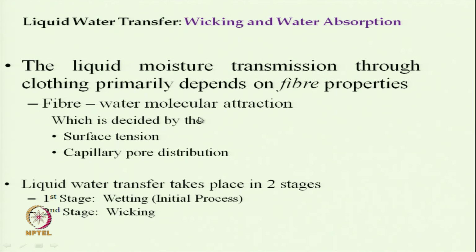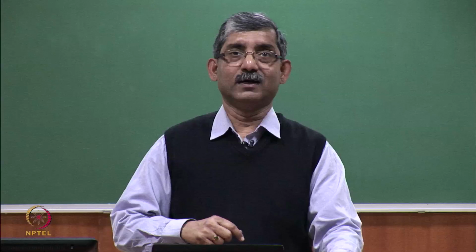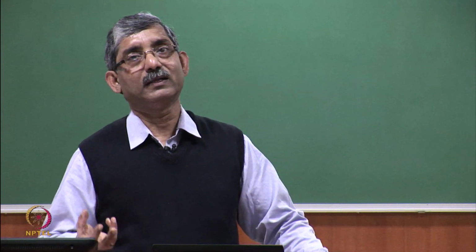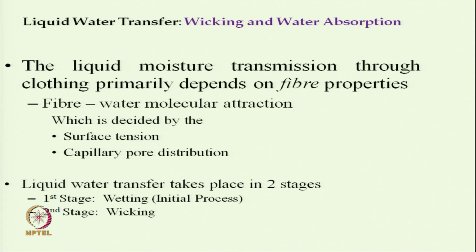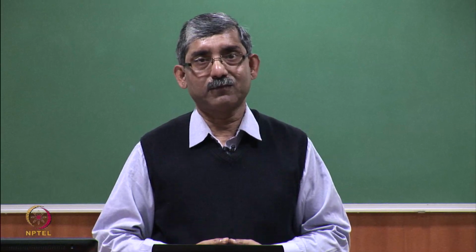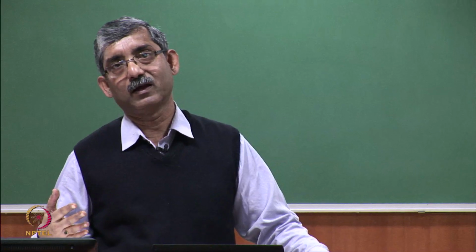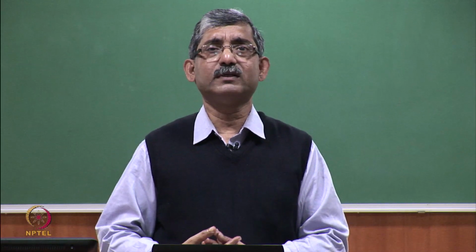So, the two principles are there, wicking and water absorption. By the term wicking we mean that the water from one place will get transmitted to another place without water logging in those pores. So, water will not remain in the pores between the fibers, but water will get transmitted from one place to another place, that is called wicking. And water absorption means which will retain water within the structure.